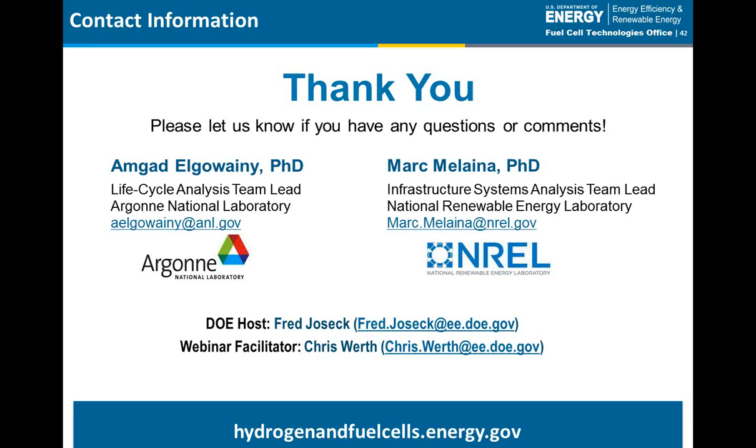Okay, and are these models adaptable to mobile refueler concepts? This concept is being utilized in Japan. For H2Fast, yeah, if you put in the cost the right way, you would be able to assess the finances for that particular type of station. I would say to some extent, yes. Outside really the cost of packaging and having a container, yes. I should mention that mobile refuelers have much lower performance metrics. For example, how many back-to-back they could satisfy and all of that. So they may be just a somewhat different type of station, but they can be modeled with these tools.